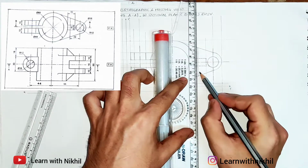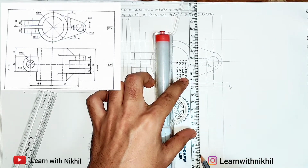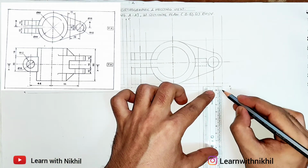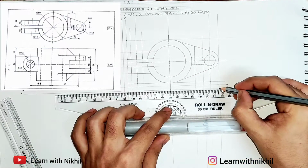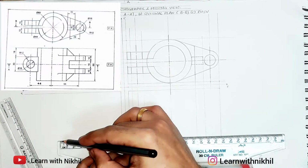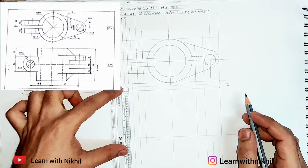Now we are done with the front view. We'll take the projections downward to the top view. We have to draw the section lines in the front view. I'll do it. Now the height is 66 millimeter. In the top view it is given, so I marked a point. I'll draw the parallel line through it. I'll extend these lines.